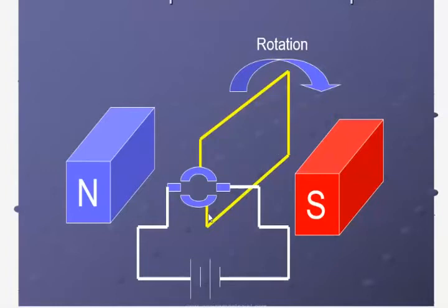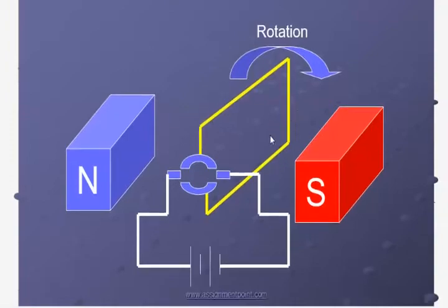So to prevent the deformation of the coil under action of magnetic force, we wrap the coil over the solid strong frame, that is called armature, and this frame is capable of rotating about an axis, and that's why as soon as the current passes through the coil, the magnetic force shifted over the armature and armature keeps on rotating. That's why mechanical energy is produced.